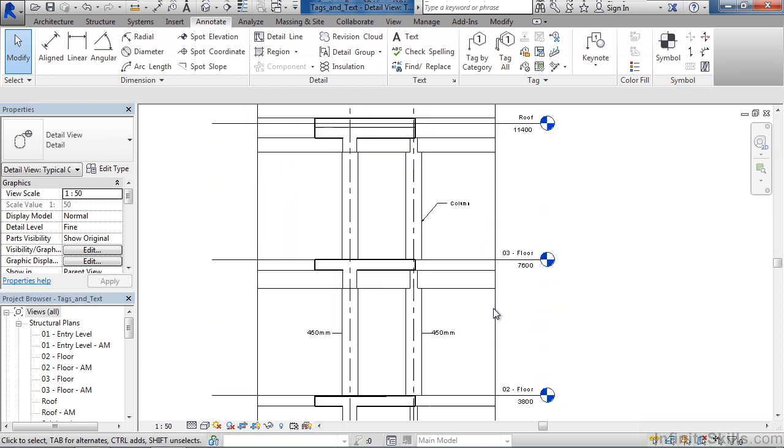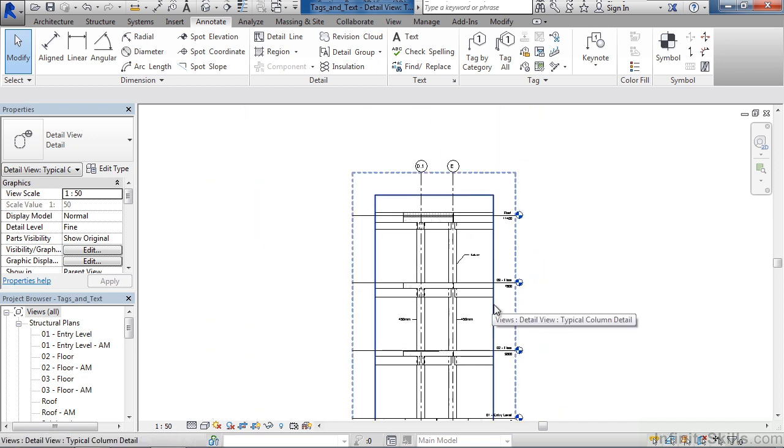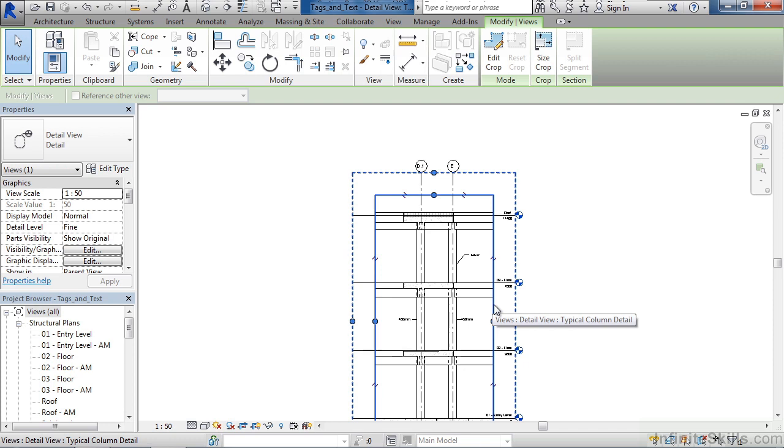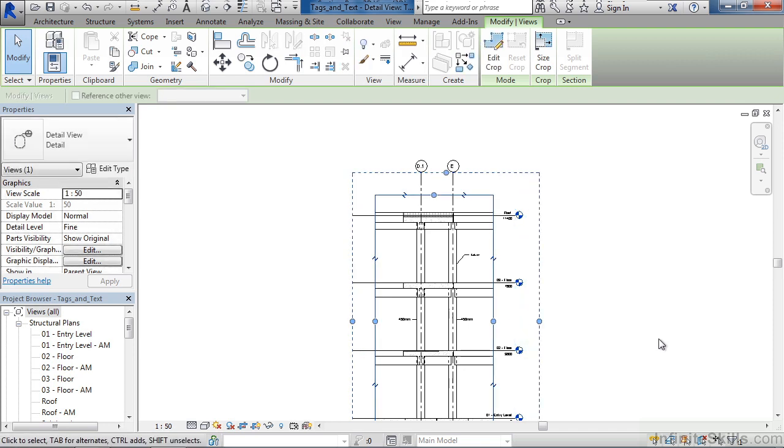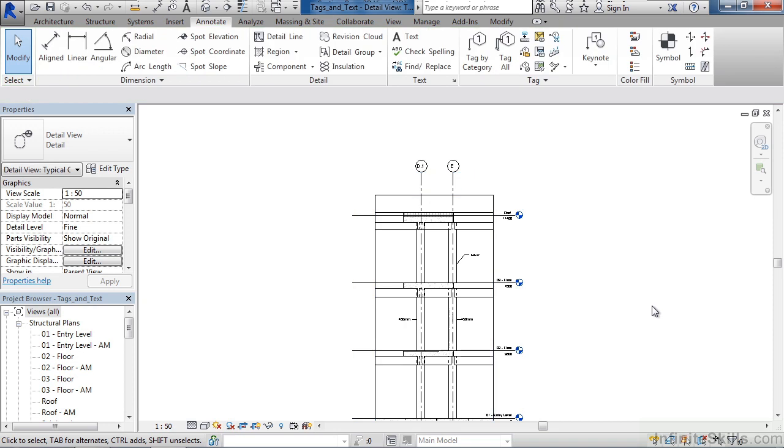If any of your text or annotation goes outside of that dashed line, that entire string of text will be cropped or not visible. So if you need to enlarge it, one way is to simply select the actual crop box, then drag the drag handle on the annotation crop to be something larger or smaller so the text is not cropped off. To deselect, click in the background, and then turn off the crop box or hide it using the tool on the view bar on the bottom.